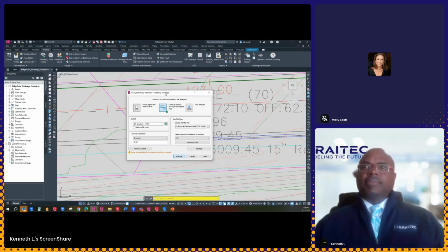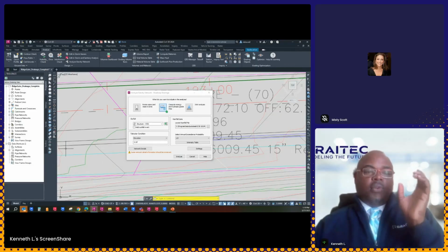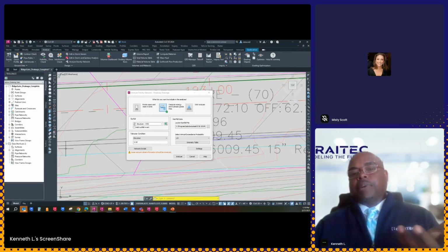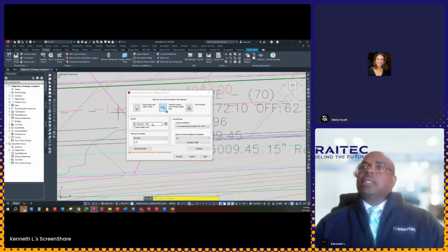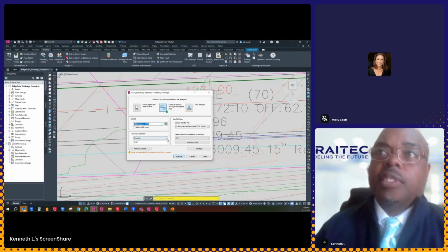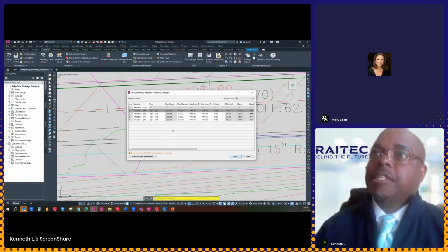And there's some workflows that make reference to it, but typically you create that roadway geometry, and then you set up your inlets and perform an analysis. Pretty straightforward. Create your pipe network, same thing. You have the ability to select structures, outfalls, tailwater condition, network details, and it gives you nice structures.